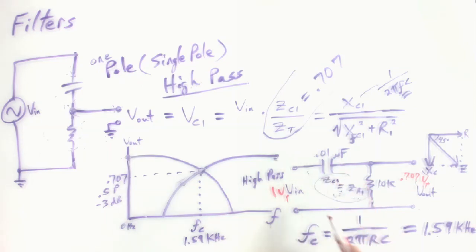And then for this example, now we have the high pass. It'd be the same thing, but you would start high. You would put 1 volt peak at a high frequency so that you have essentially the 1 volt peak output. Then as you decrease the frequency, your output would drop to 0.707, and that would be for your high pass test.